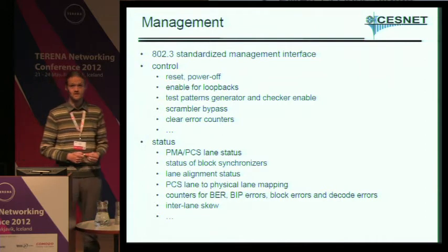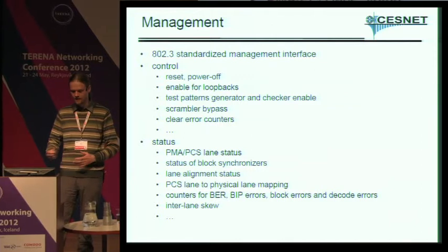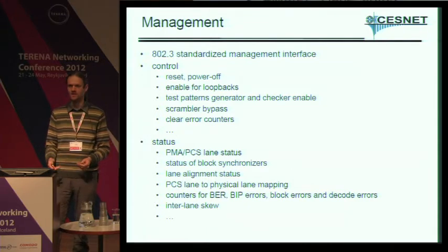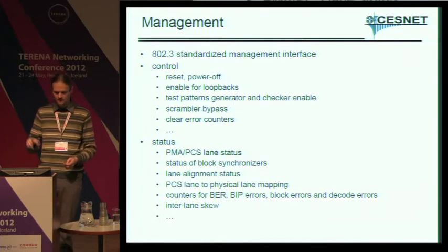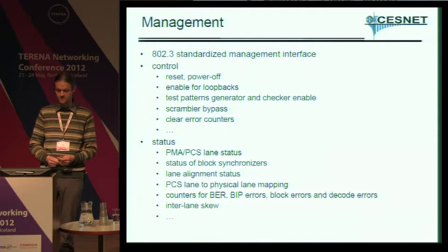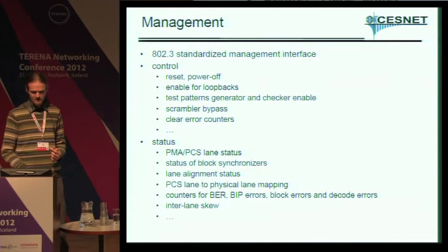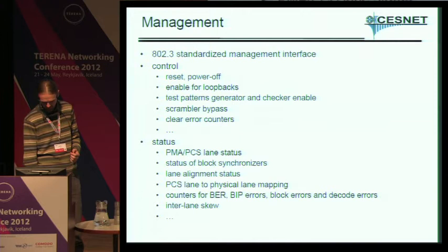The management in 100G remained almost the same. However, several fields in the address space have been added, namely the lane alignment status, the mapping of PCS lanes to physical lanes, because they can be switched, and the interface has to deal with that correctly. So this management is just a little bit bigger than it was, but nothing really new is here.